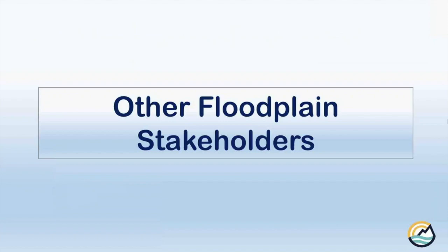If a person wants to develop a pond on their property, does that need a permit? The short answer is if it's in the floodplain, yes. Remember, development is broad. It's any man-made change to real estate. So even though they might be digging a hole and making it better, you're changing the way water flows. You're changing where water goes during those flood events. So we want to take a look and make sure that one, it's going to be safe, and two, you're not affecting other people negatively.